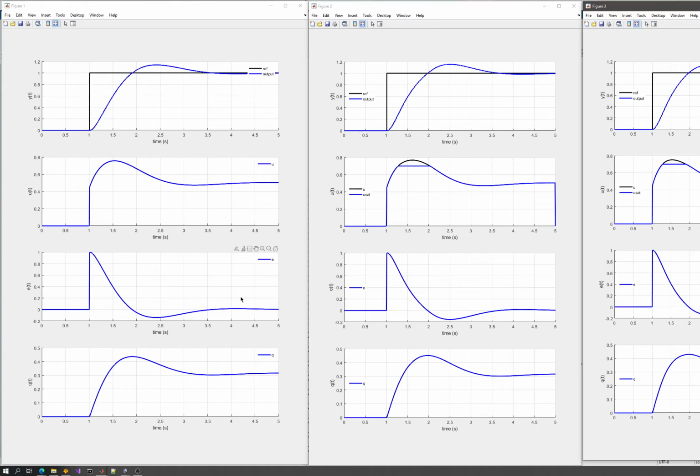But settling time, rise time, and those things are requested to be low in value. So the faster the system, the better it is. But sometimes the application itself has some restrictions on it, namely saturation, slew rates, and so on. So if you think about an industrial application, probably you will try to speed up your system, but that's all. It has a trade-off between these kinds of properties, let's say saturation and control signal values, and speed. So this trade-off is up to you. And if you change the settling time, the whole design process will vary, so you have to choose the optimal solution, and it takes a little bit of practice and some knowledge to accomplish the best,